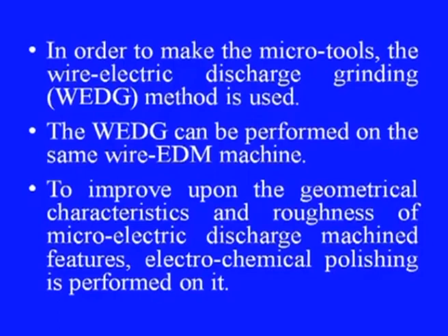In order to make the micro tools, the wire electric discharge grinding, WEDG, method is used. The WEDG method can be performed on the same wire EDM machine. In order to improve upon the electrical, geometrical characteristics and roughness of microelectric discharge machined features, electrochemical polishing is preferred on it.